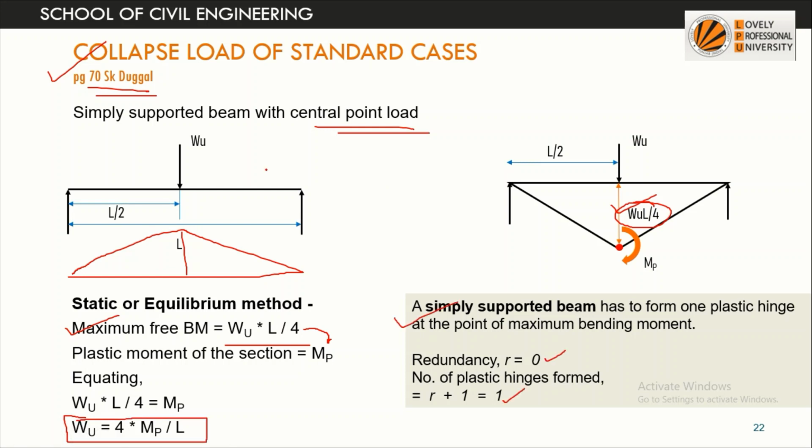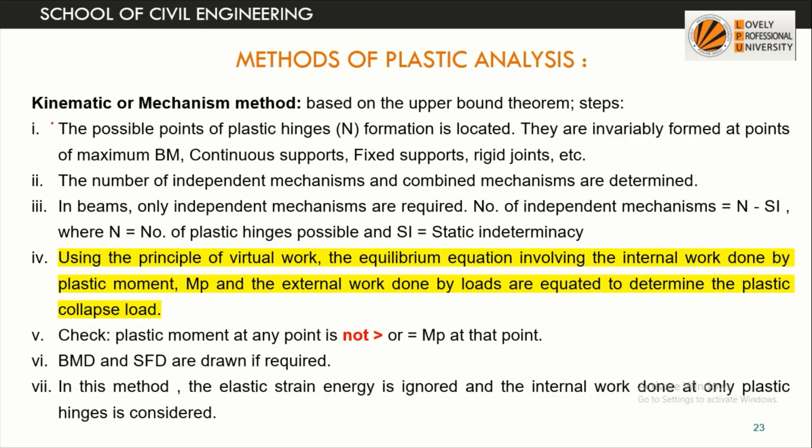So this is a simple case. In this, what we have to do is equate the free bending moment diagram with the value of the plastic moment, so we'll get the collapse load. Then this is the second method. It is based on the kinematic or mechanism method.